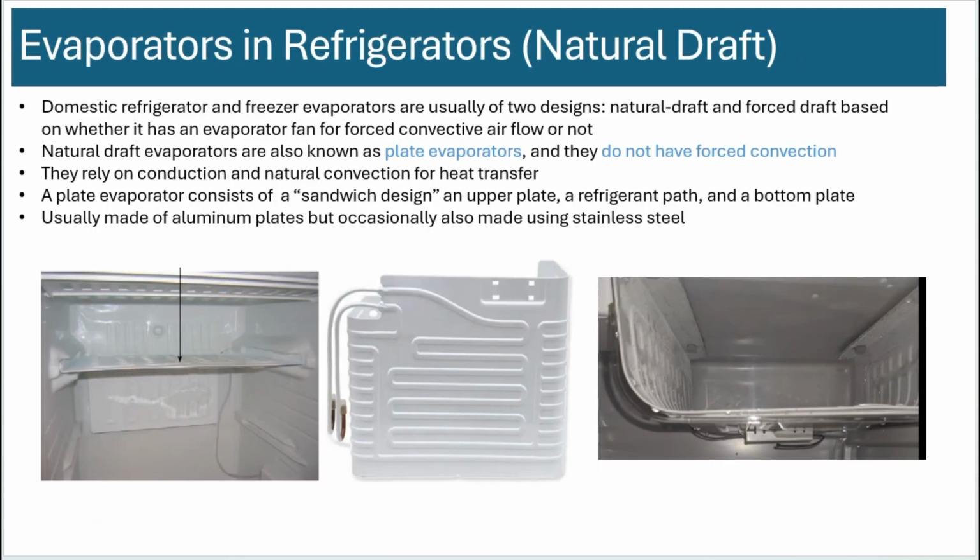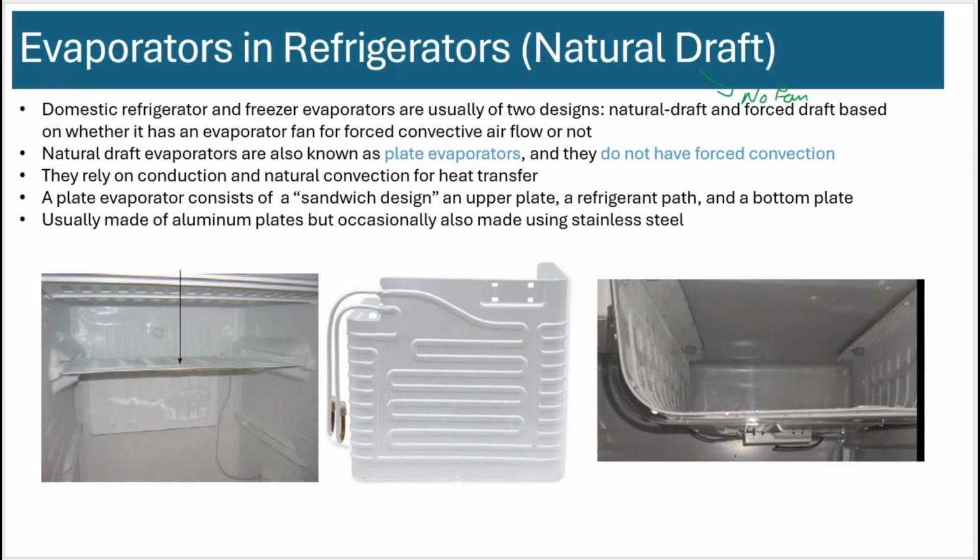All right, so now let's look at specific heat exchanger designs in refrigerators. Let's start with evaporators. Evaporators have two types of designs. One is natural draft, means there's no fan, no fan, okay? Since they don't have fans, they rely on direct contact, which is conduction, and natural convection for heat transfer, okay?